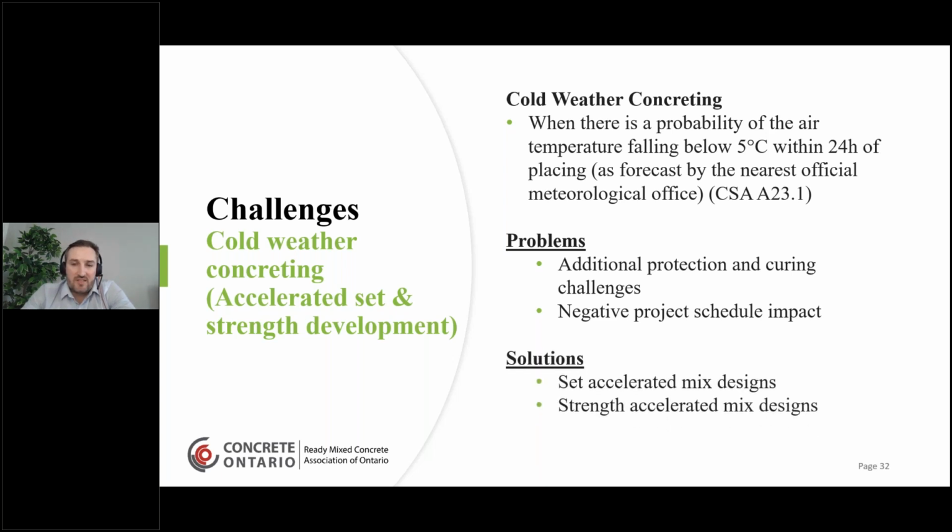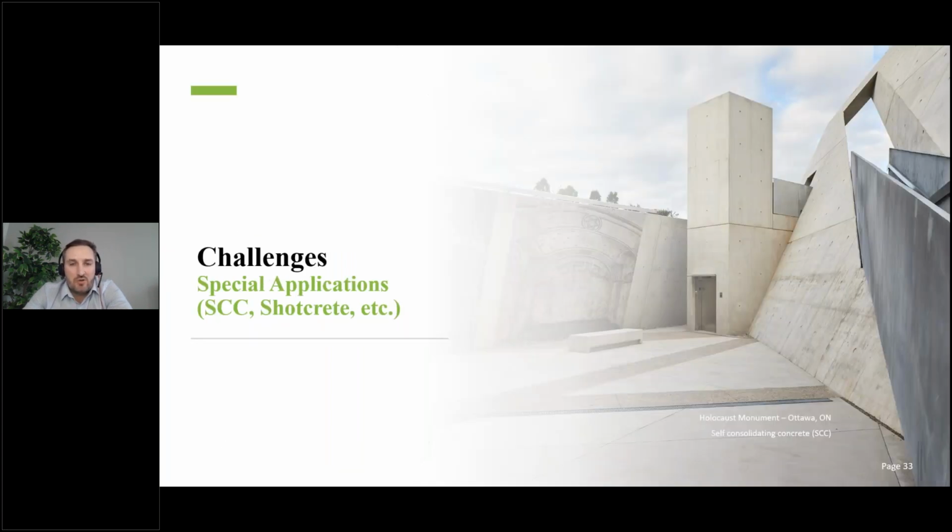So the ready mix industry does have a lot of solutions. There's set accelerated mix designs, there's strength accelerated mix designs. There's a lot we can do to change the properties of that mix design to allow specifiers and contractors to keep their schedule, but that will have a negative impact on the mix designs used because you are getting all those benefits of being able to pour concrete in minus 10, minus 20 degree weather.